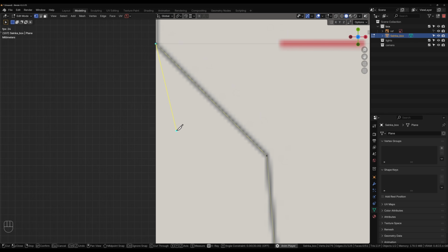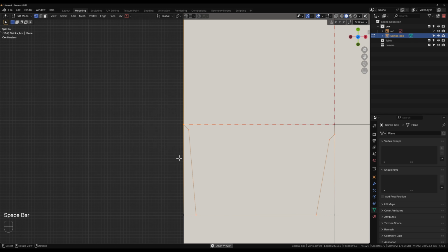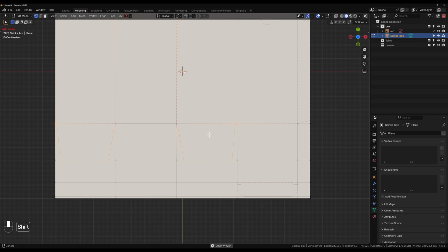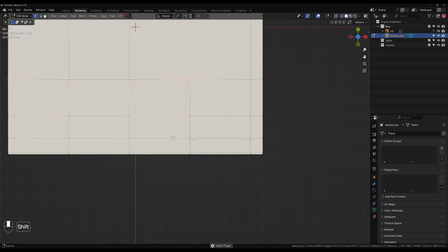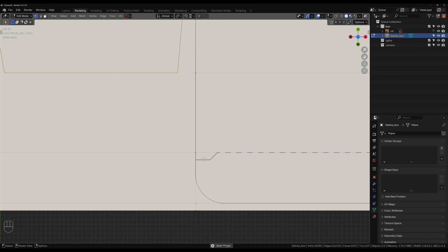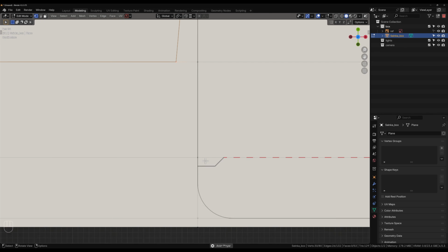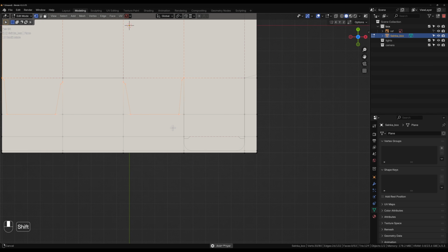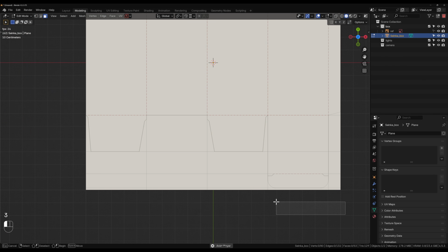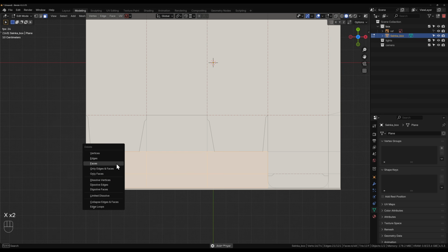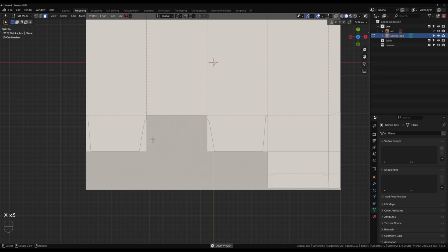Go like this and into the corner there, right click, spacebar to apply the cuts. So there we go. Now I could start cutting this and do my little edge, but what I'm going to do first is go 3 for face select, and I'm just going to get rid of all the extra faces here that I don't need, that's outside the die.